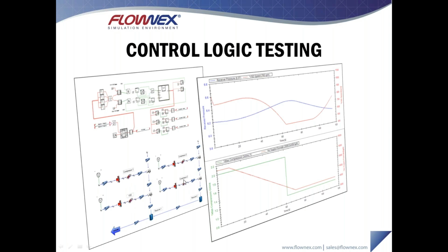The baseload compressors just simply operate on or off. These are then coupled to two receiving tanks, which have a line connecting the two of them, and then a supply line out of that. The control system itself is responsible for managing the operation of this plant. The air supply fluctuates over time as the systems that use this air turn on or turn off or go through different load scenarios.